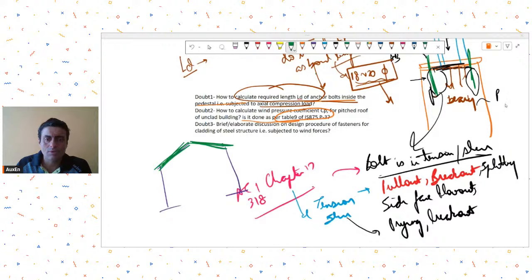Let me just go to table 5, table 6. Yeah, of rectangular clad buildings. So 5 is for walls, 6 is for roofs, but it has to be a rectangular clad building. For open type of structures, you may refer to table 9, which is for freestanding roofs, and in that you will get your shape. So I guess, yes, you could use table 9 for it.